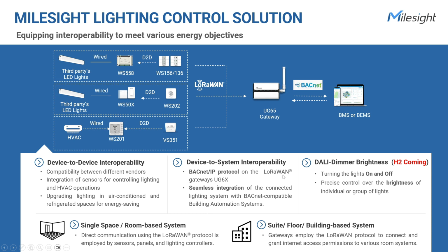Let's make Milesight's office building an example. It has been equipped with a revolutionary new lighting system that uses light differently. We installed a mix of light controllers, presence and occupancy sensors, and wall switches across a single 8,600 square meter office space, everywhere in the meeting rooms, public areas, corridors, dining areas, and washroom. In 5 years, if the business expands to reconfigure its layout, Milesight can make it easy to add supplemental components without having to start from scratch. In this case, the LoRaWAN-based devices can be wireless and battery-powered, minimizing the burden of installation.